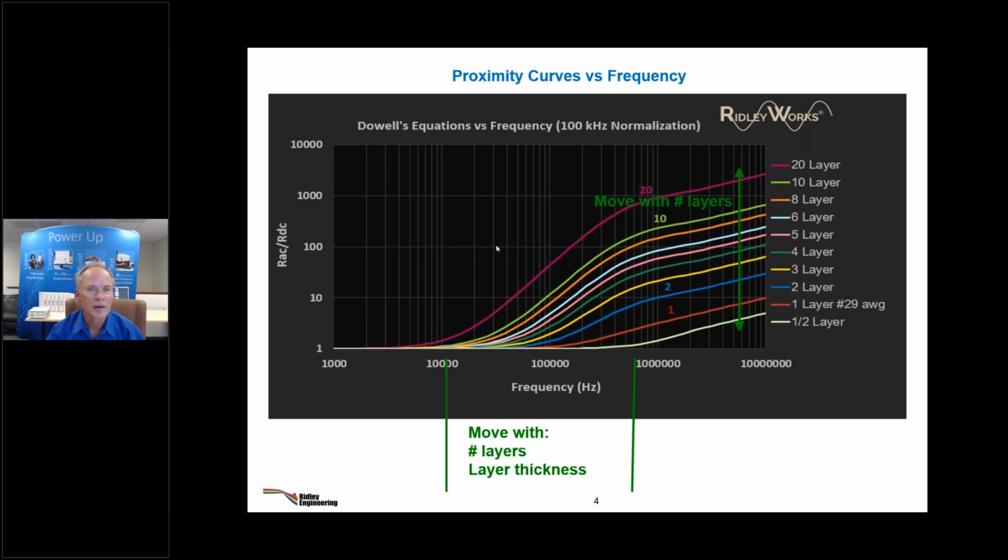Can you extract inductor and resistor values using the Ridley box? Okay, measuring AC resistance is hard. If you're down in the milliohm range, there's too much inductance in the setup for any analyzer. Even the old warhorse, the HP, couldn't pull it out. Have we done that? Yes, we have. You can do it for transformers, where you can short the secondary and pull out the AC resistance.